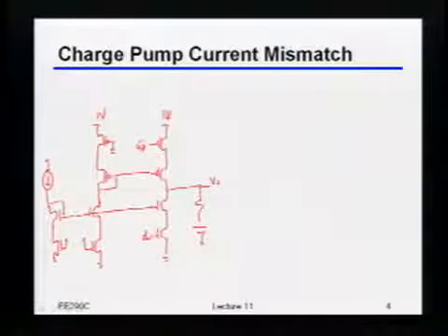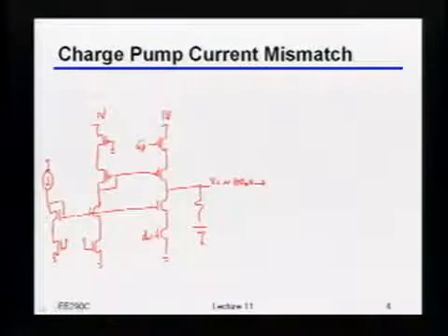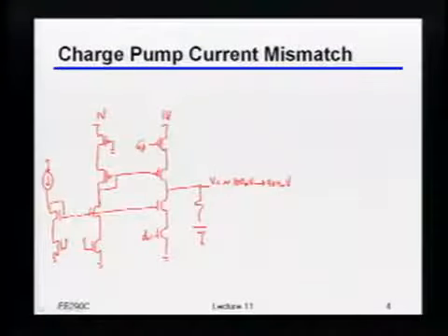So let's say we use a reasonable V star. Let's say that's 100-ish millivolts or maybe 200 millivolts, somewhere in that ballpark. That would basically say that you want this to range from something like about 100 millivolts or so up to maybe about 900 millivolts. That's maybe a little bit aggressive, but somewhere in that ballpark, right?